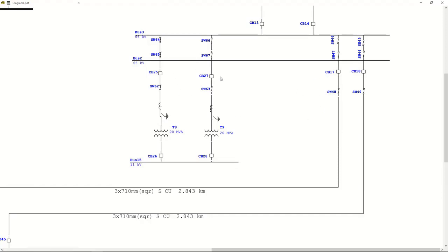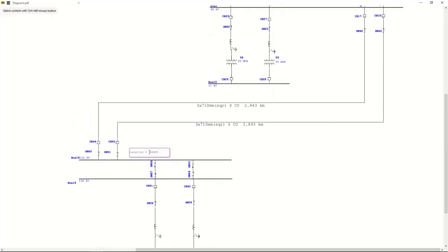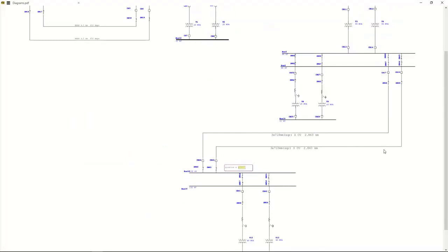Now from this substation, we also have a location that is also taking power from there. That's equipped with two step down transformers that are stepping down to also 11 kV, also rated at 20 MVA. Then we move from there, from this Busbar 4, substation 4, to the last Busbar 5 of the system. And the power system is still sending 66 kilovolt through the line.